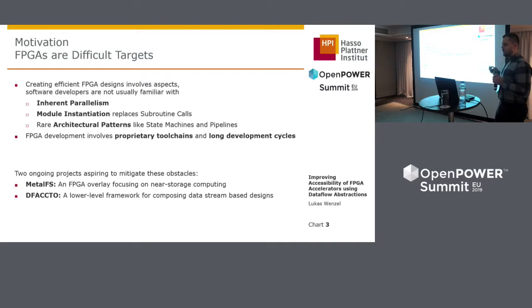You are also faced with a problem that you cannot simply call subroutines, because this kind of thing on an FPGA level usually behaves like an inline function. If you call a function multiple times, or in the right language, instantiate it, you are faced with a very large design for perhaps no great utilization of your hardware.